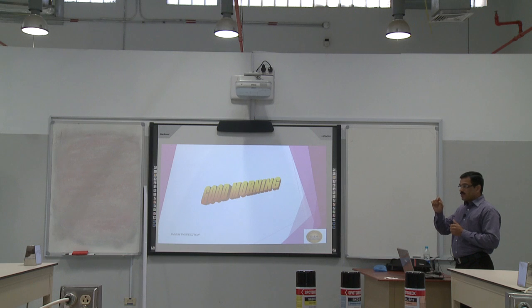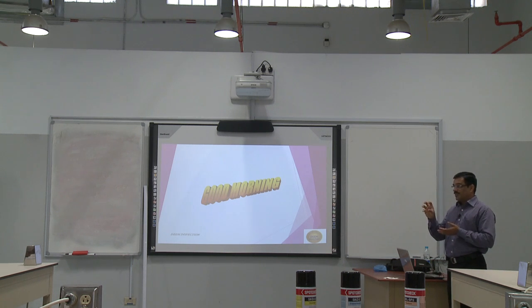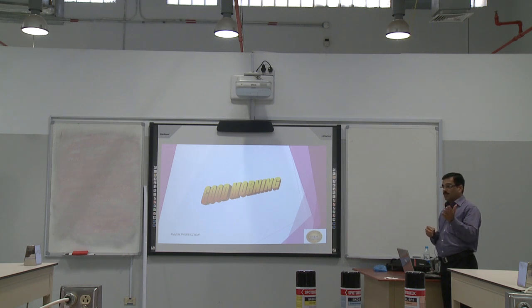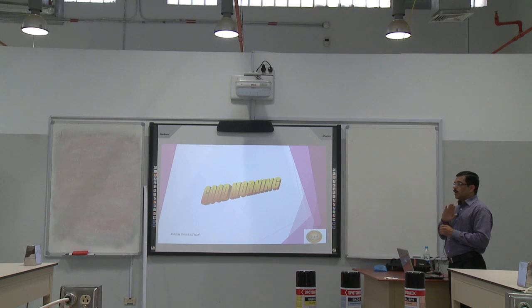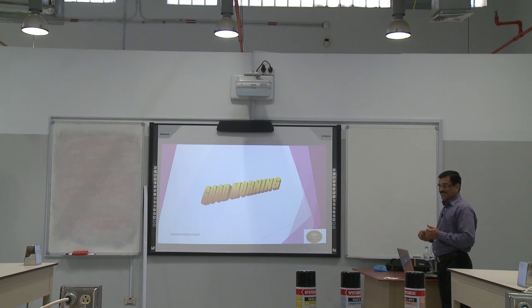Do you know which is porous? Porous means material with an absorbing nature, like a sponge, our skin, wood, which has an absorbing character. Such material we cannot use. So, all other material, even ferrous or non-ferrous, magnetic or non-magnetic, any material we can apply penetrant testing. No, wood is a porous type.